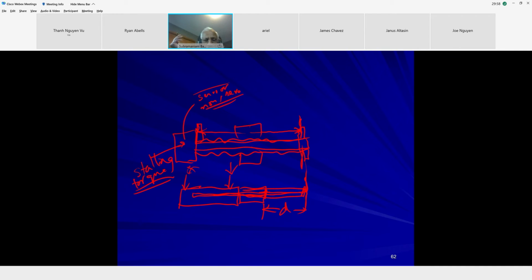Now, in the case of air, when I apply pressure here, there is no electricity, nothing. It applies the force to the cylinder and pushes the load to this point, and that's its extreme, and it will keep applying the force on the object. If you collapse the air here, that pressure or force is gone, but the part has moved to that point. There is a home position and there is an advanced position. Exactly, home, advanced. In the case of an air cylinder, you're simply applying the air.